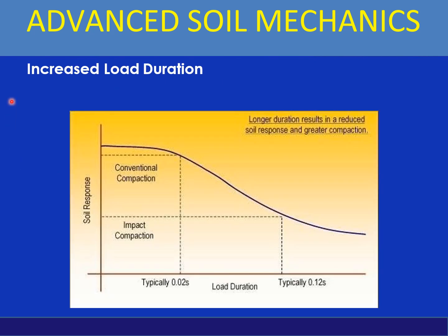Now look at that increased load duration. What is happening? You can see that with the increase in the load duration, the soil response is reducing. Longer duration results in a reduced soil response and greater compaction can be achieved. So with the increase in the load duration, there will be a reduction in the soil response and better compaction can be achieved in that case.